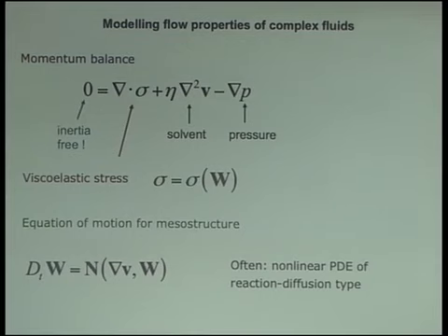And then there's one final mental switch that we need to make in modelling these viscoelastic fluids as compared to people from the traditional fluid mechanics literature, which is that very often we're in the regime where these viscoelastic stresses are so large compared to any inertial forces that we can effectively take the limit of Stokes' creeping flow in which the inertial terms are unimportant.